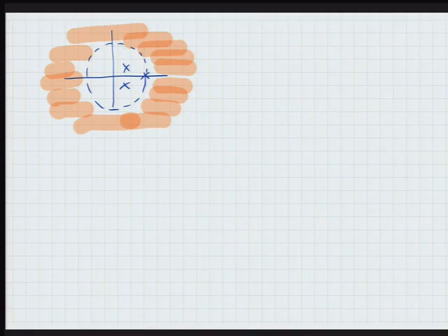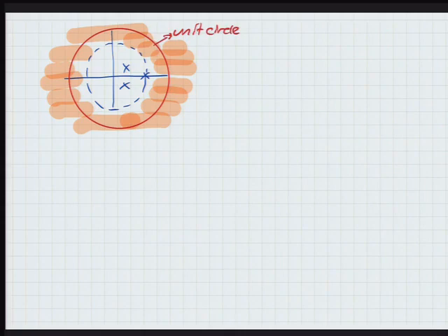All right. So, and then we want the unit circle to be part of the ROC. Okay? So that means the unit circle should lie somewhere here. Unit circle. All right, so this is a picture where things work, right? Things come together. Unit circle is in the ROC, and ROC, since the system is causal, starts from the outermost pole and extends to infinity.